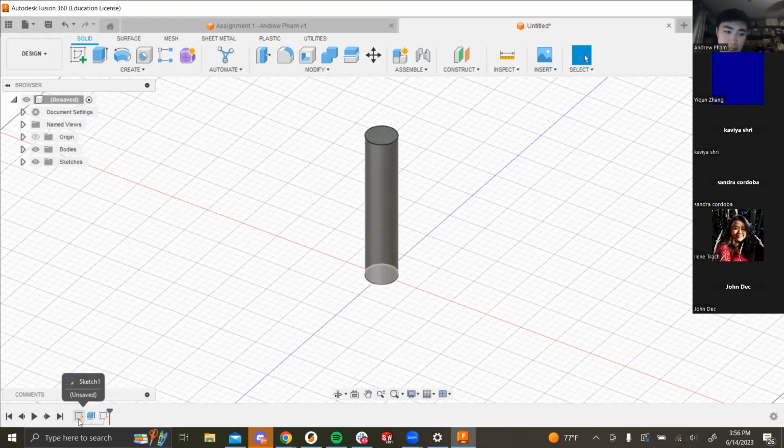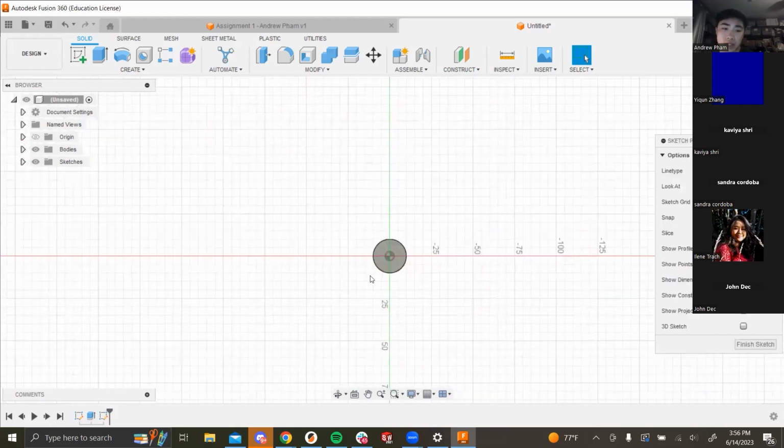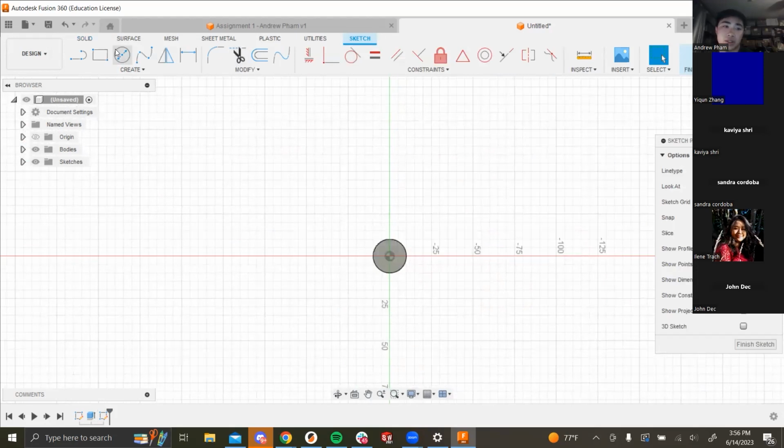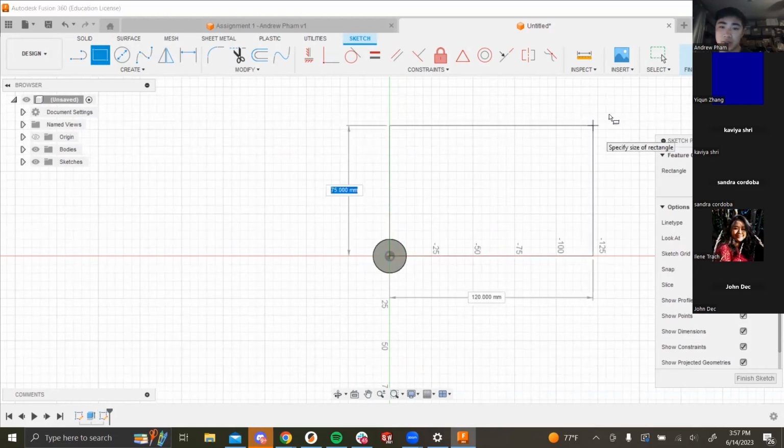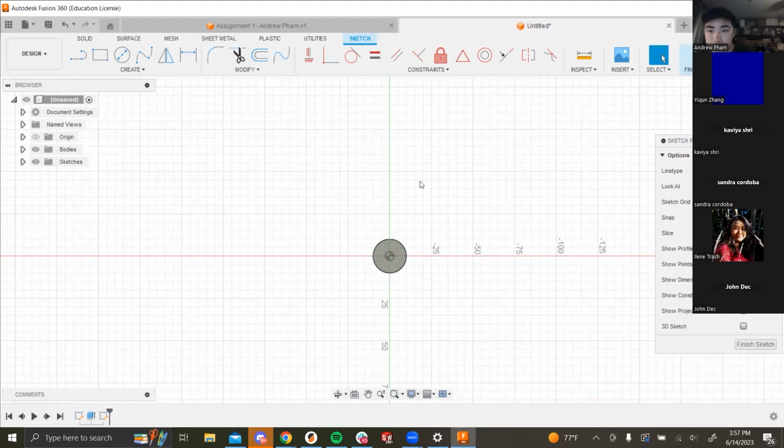So now that we changed this, we can go back into our other sketch. Sketch 2 is the empty one with the hammerhead that we were going to do. We want to make a rectangle again. Before we were using the 2-point rectangle, and it basically would make a rectangle from one vertex to the other, and you just stretch it out from the corners.